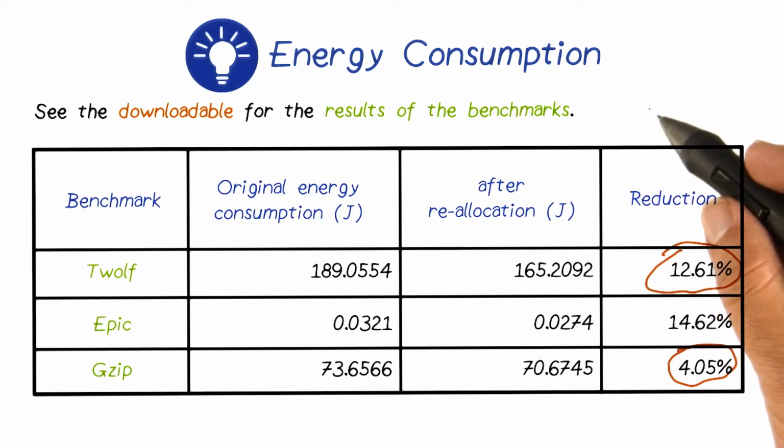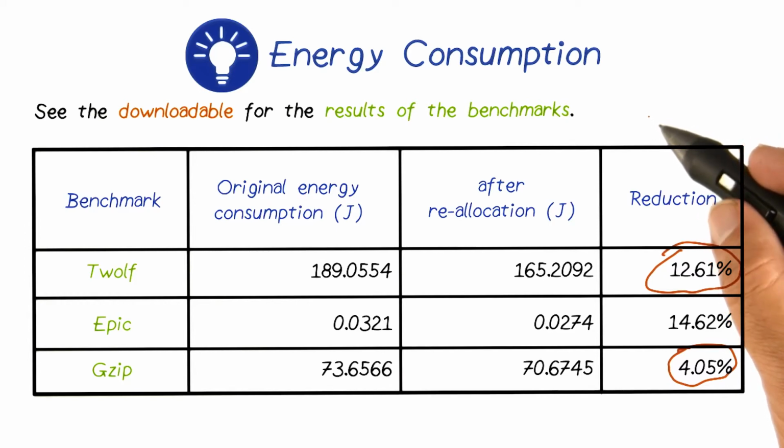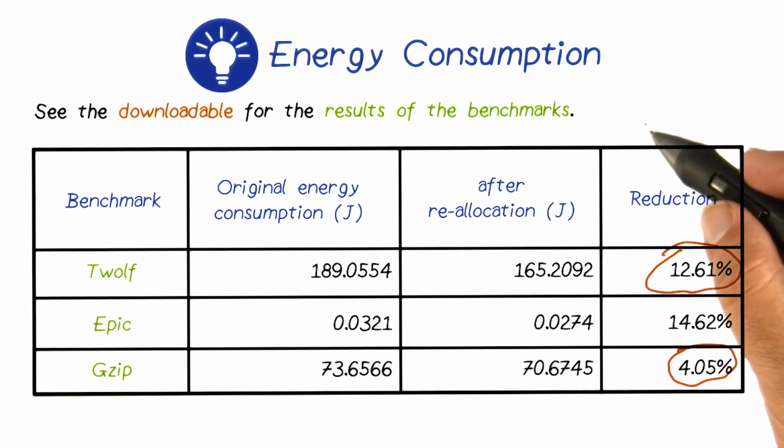And so to conclude, in this first research artifact on embedded systems, what we saw was that by cleverly redoing the register allocation at the binary level, which is what we call post-pass, we are able to reduce the cache activity, although we are not able to reduce the total execution time that much, because all those latencies are already hidden by the reordering of instructions and so on. Due to the reduction in the dynamic activities, there is an overall energy reduction, which is really important for embedded processors.